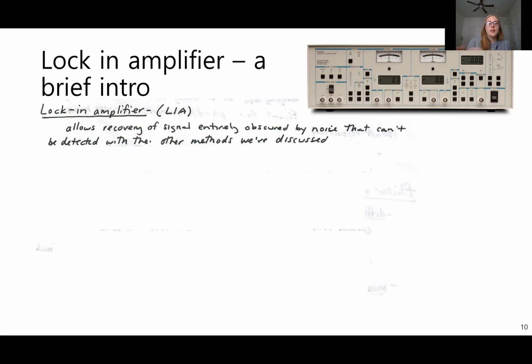So I think most of you in lab 3, when you were varying the signal to noise ratio, were able to detect a single peak in the frequency domain for your square wave at a signal to noise ratio of about 0.3. In contrast, the lock-in amplifier is able to detect signal to noise ratios 2 orders of magnitude better than that, so roughly around 0.01. So this is an improvement by a factor that can sometimes be upwards of 1,000, or 10 to the third.